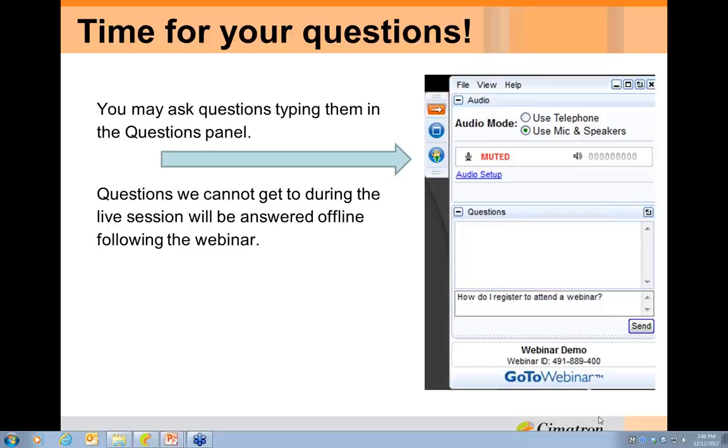And here is what looks like it might be the final question. Do you have to have your parts quick split in order to use ECO Manager? No, you don't. You saw me using it a lot, but because quick split is so vital to the process of how we pass stuff down into cores and cavities, that's how we know what goes to what part. Is it assigned to the blue? Is it assigned to the pink? Or many of the other sets. And so in the cases where I wanted to update, I needed to do that, so it knew where to take what surfaces.